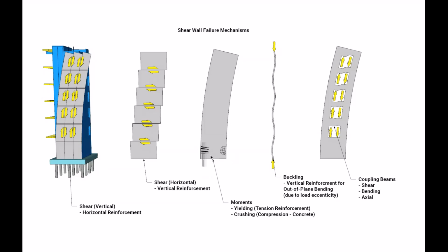This check is typically the most critical, and we'll go through a short preliminary design stage check for early stage designs next. Consideration will also need to be given to buckling, especially for slender walls, and also when we introduce openings, we will need to consider the design of our coupling beams, which will have the job of sharing the horizontal load between the two vertical piers.